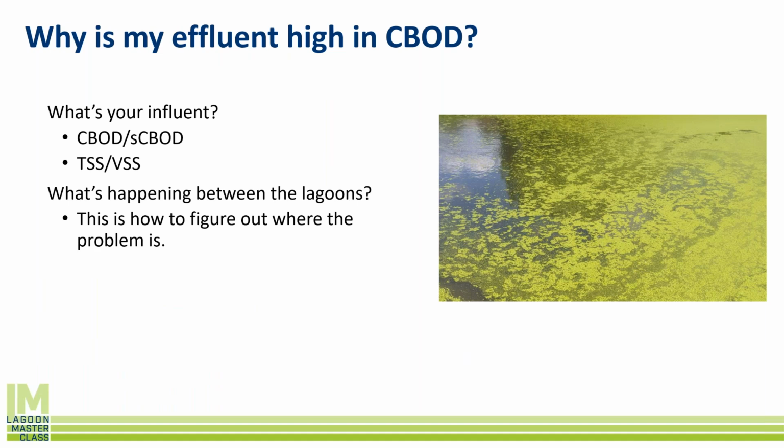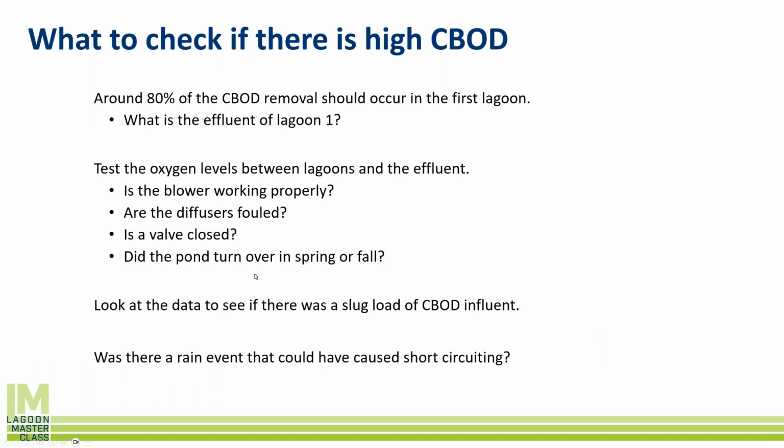That can be really important in terms of diagnosis, because maybe Lagoon 1 and 2 work really well, but maybe Lagoon 3 is filled with sludge and it's actually causing problems. So we need to sometimes look at sampling between lagoons. Sorry about that.